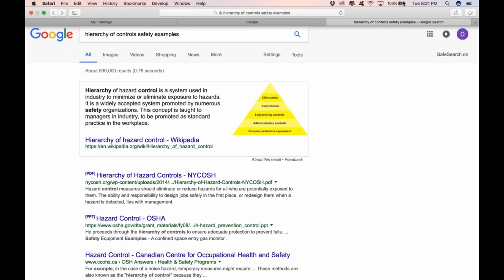Okay. And then, of course, also it could be SCBA, self-contained breathing apparatus, like we're talking about right now. They're required for unknown atmospheres, oxygen deficient atmospheres, or atmospheres that are IDLH, immediately dangerous to life or health. So the highest level of protection, folks, is the SCBA that you see. That's the first highest level of protection. The second highest level of protection will be the supplied air mask. Okay, so those two are air supplied. So self-contained first, supplied air mask that comes on the airline would be the second option.